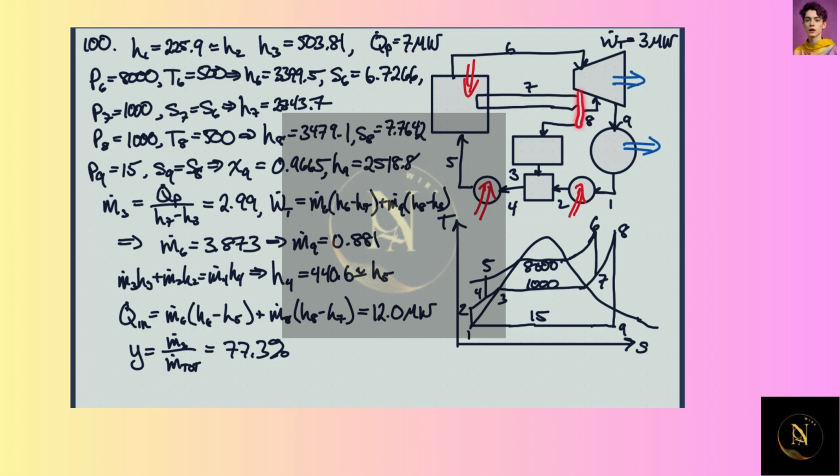And then we have some of that also coming off into the process heater, and then we have a mixing chamber here. Stuff coming out of the turbine goes to the condenser, then goes to the pump to get pumped up to the same pressure as here, so all this can get mixed. Then it goes to another pump to pump it up to the boiler pressure, which then heats it up and sends it back to the turbine to get work extracted out of it.